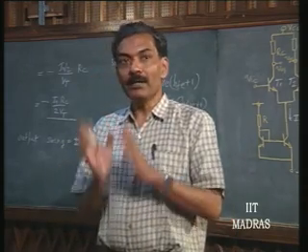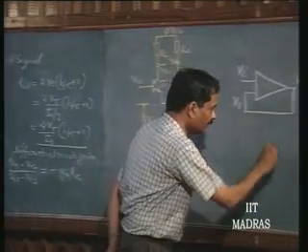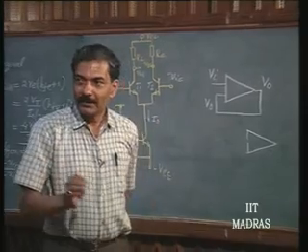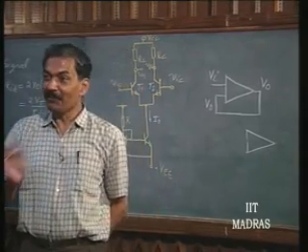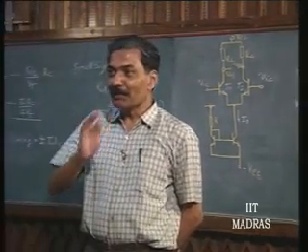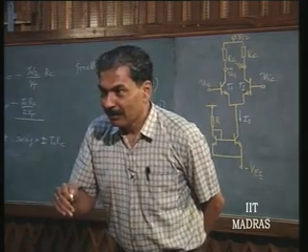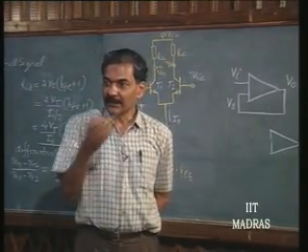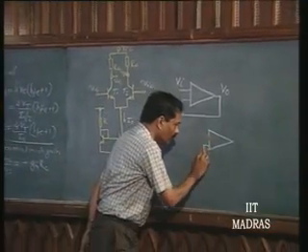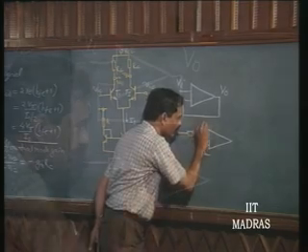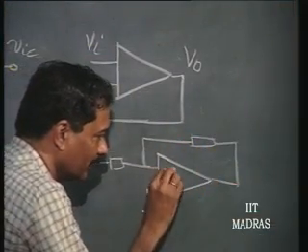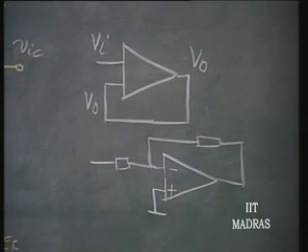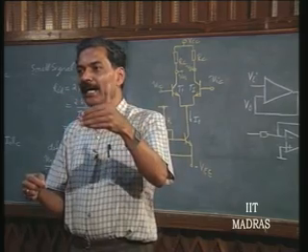If you say that I will never use this amplifier in unity gain mode, where is it least severe? Where there is no common mode? No, open loop is a situation where there is no feedback, so you are not going to bring in any common mode problem for yourself. Where there is an application where it automatically comes in, but with less severity than this, is the inverting mode of operation, where one end is connected to ground and the other end is automatically at virtual ground.